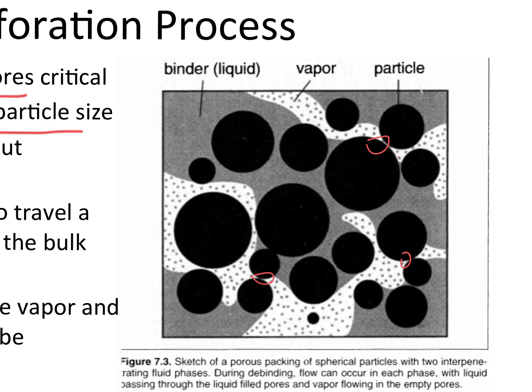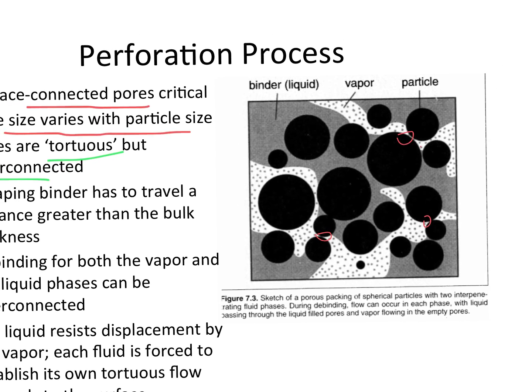All right, so you notice that a lot of that liquid, that gray liquid, is not doing anything for us in terms of capillary pressures. But when there's a very small amount of it, that's when it starts to work. All right, so the funicular state is useless. The saturated state is useless. We need those pendular bridges that are only going to exist when the very small amount of liquid is left behind, and that liquid is polypropylene or some other much higher molecular weight polymer.